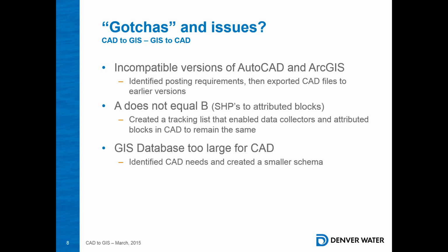The other thing I'd like to mention is not leaving any kind of connections in your templates. That was something else that really drug us down. Initially, we got this great idea: we've got all these new tools, and we want to leave these connections because we're always going to connect up to all of our mains and all of our conduits. But when you would try to start a new template, you get frustrated and just start something random, jumping off the standards. So we disconnected all connections, and that's at will for the CAD user who needs it, not for everybody, and only a few need it.